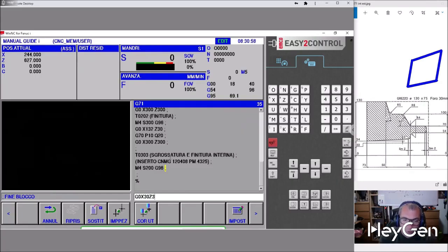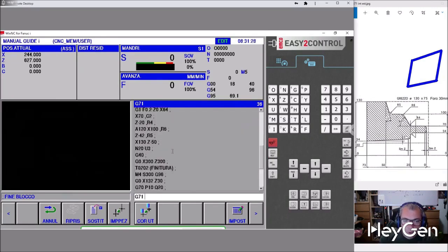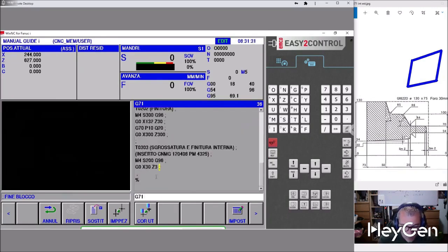If you want to be more sure about the process, you can approach the task less directly by considering alternative methods or strategies. I'm really speeding up here, which is perfect for efficiency. G71, G71. Here, we always have the depth of cut, and I need to check it. I don't remember, so U3.